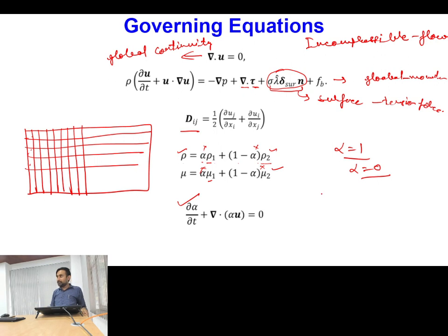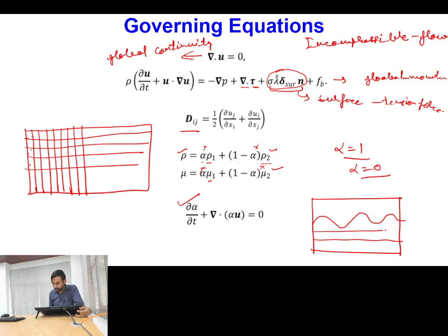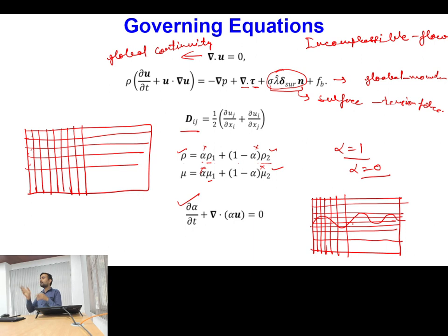So another technique you can use is, instead of going for a uniform mesh, you can go for a non-uniform mesh. Say I have some problem and it is almost clear to me that the majority of the time in this domain the interface will remain close to the center. So I can go for a non-uniform mesh where near the boundaries I will go for coarser or larger spacing, and near this point I will go for a very fine mesh structure. So this is nothing but my non-uniform mesh approach, because the sizes of different cells are not the same in each direction.